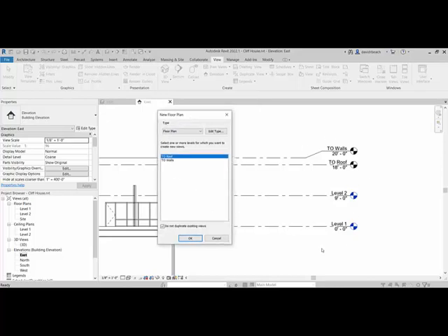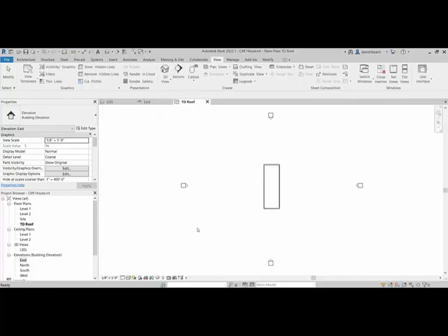Anything that you have as an elevation tag here, or an elevation target, whatever you want to call those kids, will show up in this list. But a lot of times I'm going to have things like top of column, top of masonry. I'm going to have a lot of tags in there that I don't need floor plans for. That's why they're not automatically generated. Okay, so I'm going to just label that top of roof and say okay, and that's going to add that plan view in.